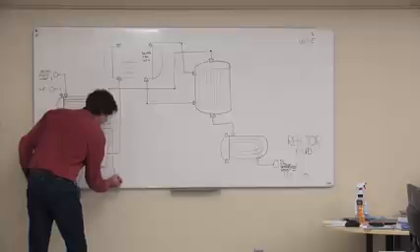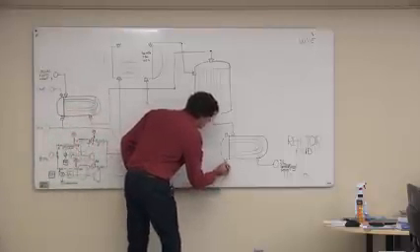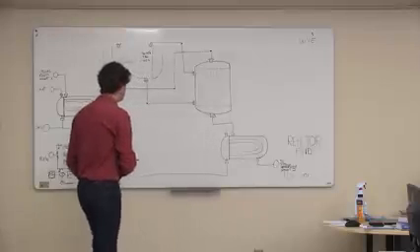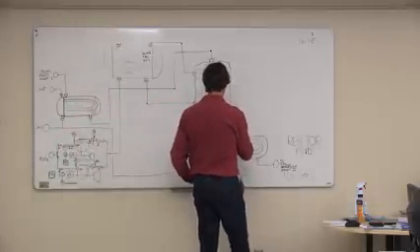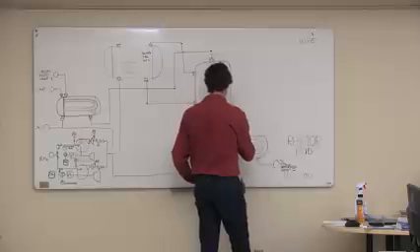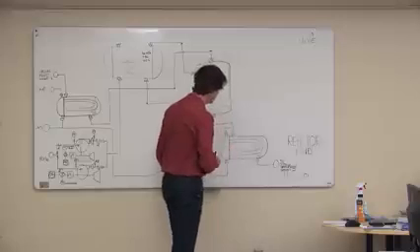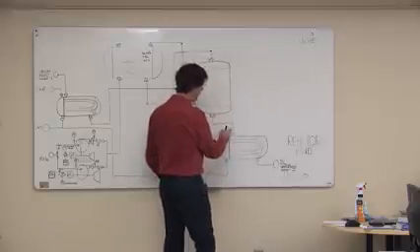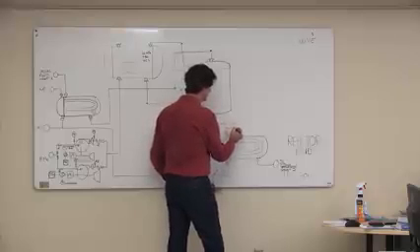Definitely not going to have enough room for the steam turbine controls. That's that. And now this is a utility, and it's horizontal, so you would think because it's horizontal, it should be breaking that line, but because that's a major process line, we're going to break the utility instead.